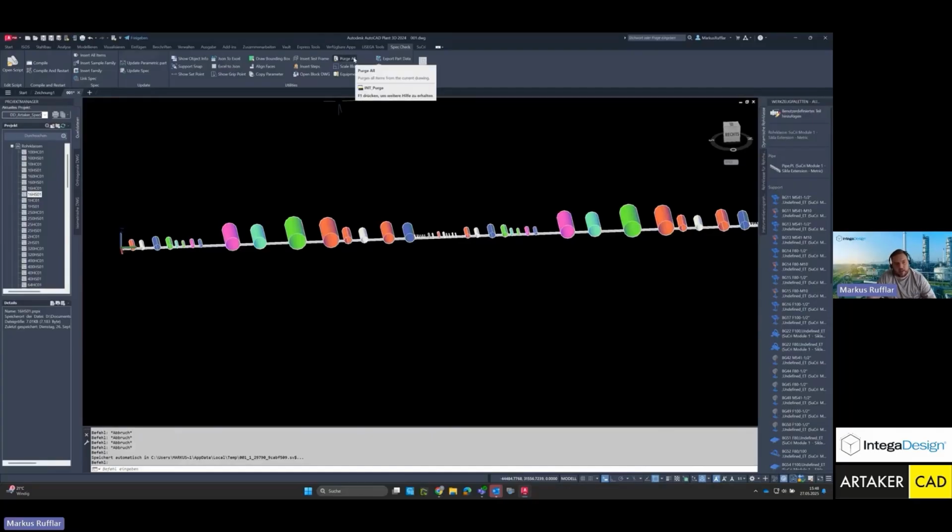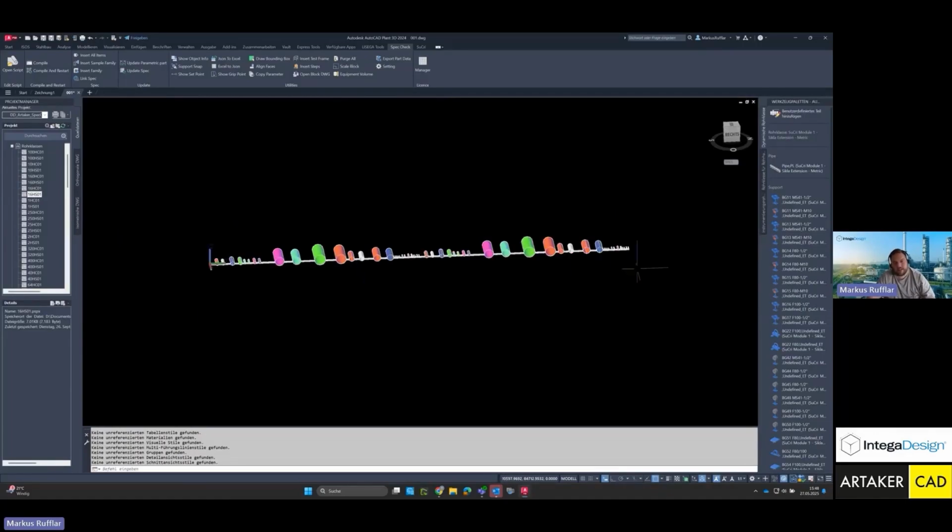Purge all. Of course, there's a purge command in Plant 3D, but this purge all command is a bit modified. The additional things are also carried out. It's also faster, so if I click here now, you can see, bam, it's basically already done. That's the cleanup command. The cleanup command has already been executed, which really, so with our purge command here, it basically cleans up and purges everything that's truly essential for component and pipe class generation or for creating checks. Blocks and so on are cleaned up. Layers are cleaned up. I think a plant audit is also performed and so on. So various nested commands one after another, and of course also optimized a bit for efficiency so that it runs a little faster. So that's what our purge all command does.